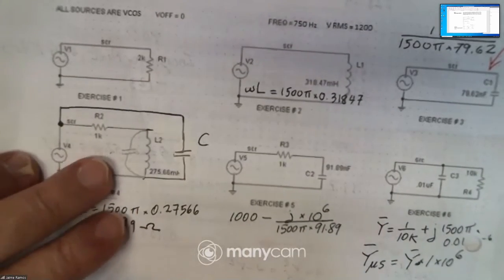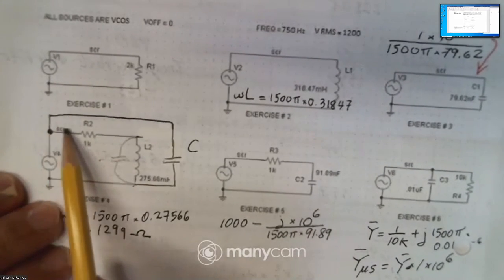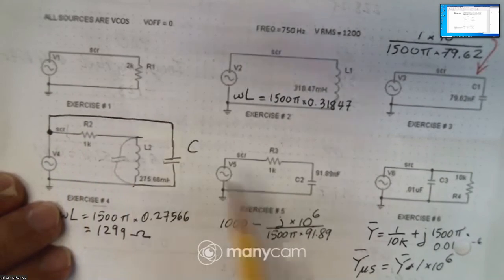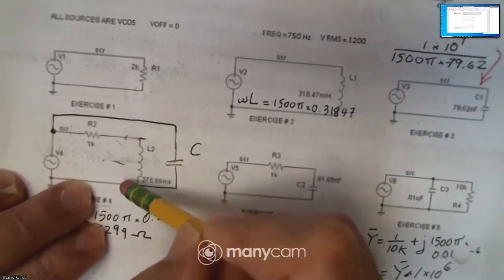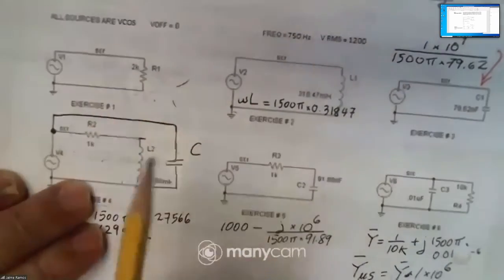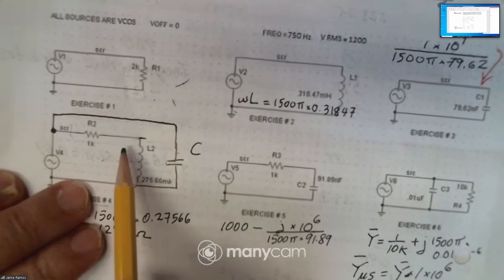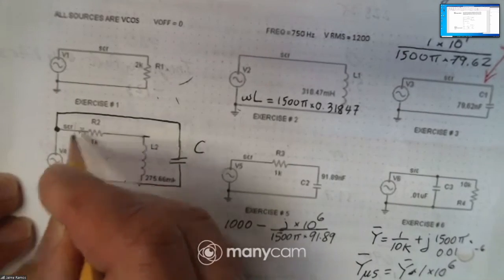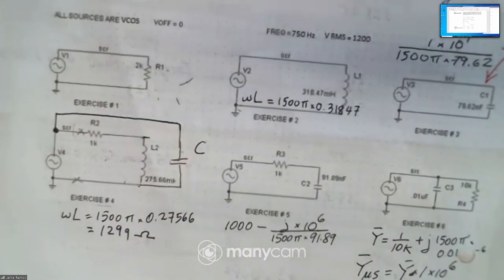So that's incorrect. This whole resistance and inductance would be like the equivalent circuit of a motor, the wiring and the coils of the motor. So the capacitor is connected across the motor. These are the motor terminals, and that's where the capacitor is connected.